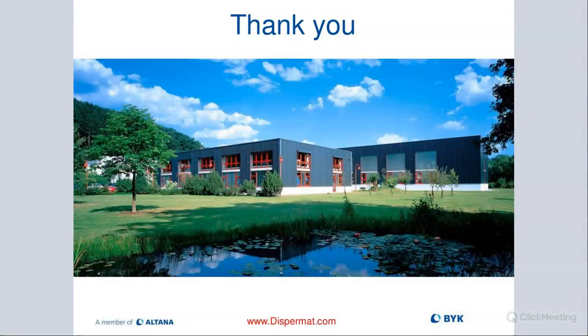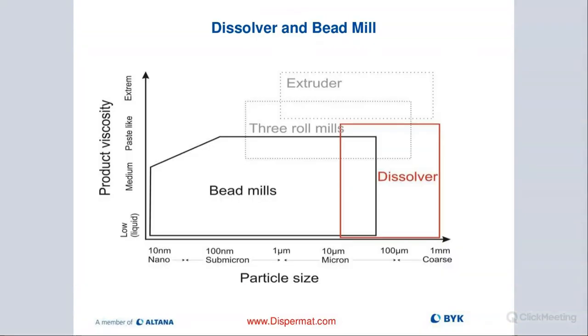Can you talk about nanoparticle dispersion at both the lab and the production processes? Sure. Nano always depends on what size we're talking about. Particle sizes up to 500 nanometers we can easily process with the basket mill or immersion mill, our TML. We can do that in our lab and in production, with pretty much standard media size of about 1 to 1.2 in most cases.